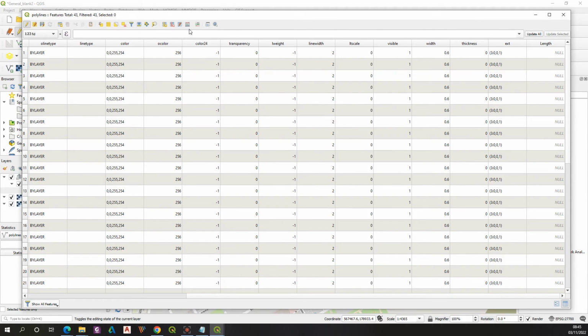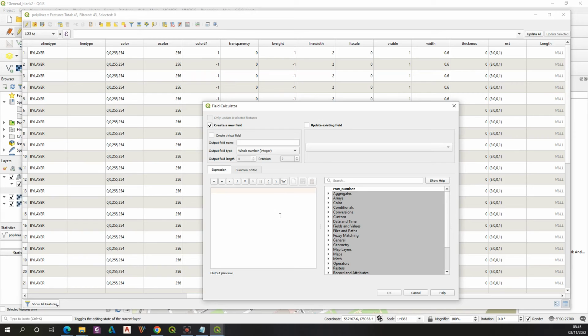Now the length column has been populated, so our next step is using the open field calculator tool. In the field calculator tool, we can simply provide the length formula, which will calculate our length straight away. But because the output looks quite robust, we don't need as many decimals as presented here, so we can embed this function in the round expression. So we can use round, and in the brackets we place the length expression, and after a comma define the number of decimals, optionally just 1 decimal. Then we see our output has changed. We've got a clearer value already presented in our output.